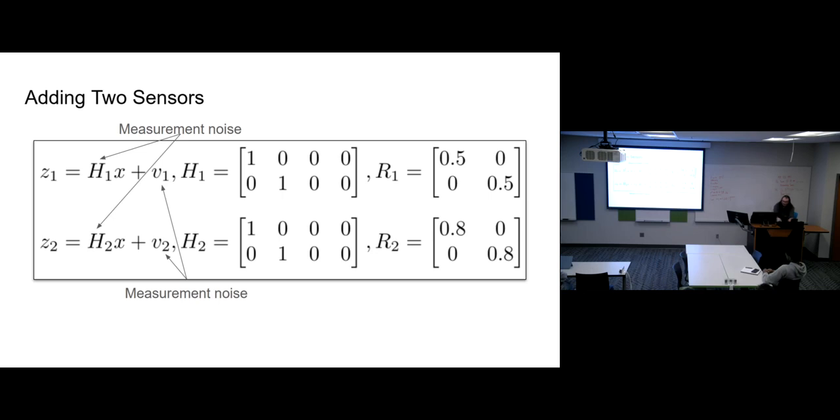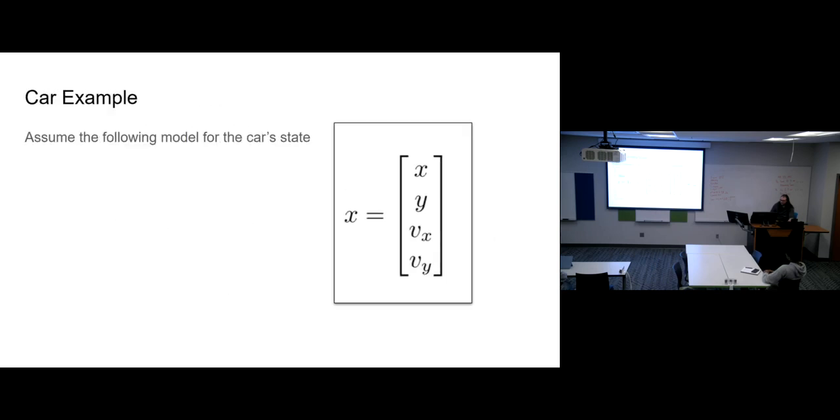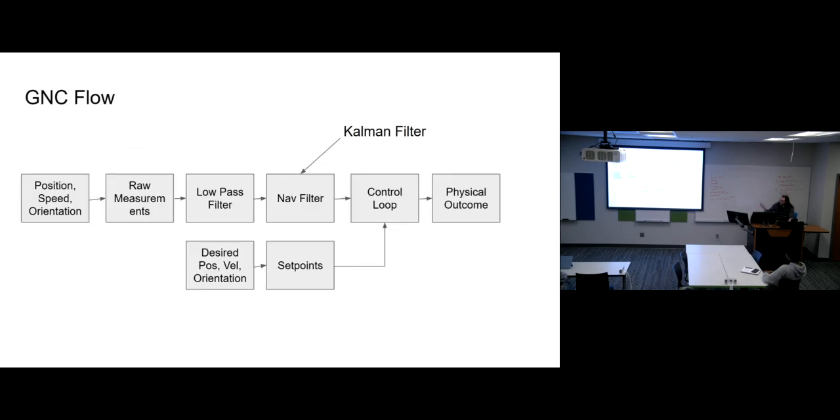Then you can pre-process it further, and that might even go into, I swear I know this direction, my notes aren't here, the low pass filter. Really, that probably should have been pre-processing of raw data. I almost seldom use any raw measurement data. I don't really trust it, honestly, without being filtered, because all it takes is raw data into your throttle control, a voltage spike puts it to full tilt or turns it off, which is something I've seen a few times. It's scary, like, wow, that just happens.